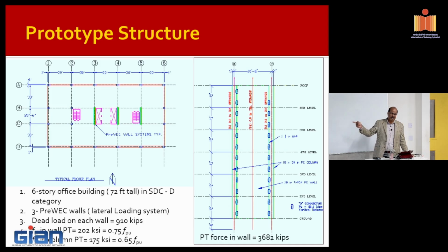What we are providing is what's known as a static hysteresis. We throw in supplemental damping. It's a deformation-dependent damping. The other one we talked about, what is inherent, we approximate as a velocity-dependent damping. So they have different damping, different mechanisms. So one is velocity-dependent. This is displacement-dependent. So the more displacement the wall goes through, the more damping you're going to get because more plastification is going to take place. What other damping can you think of in the system?